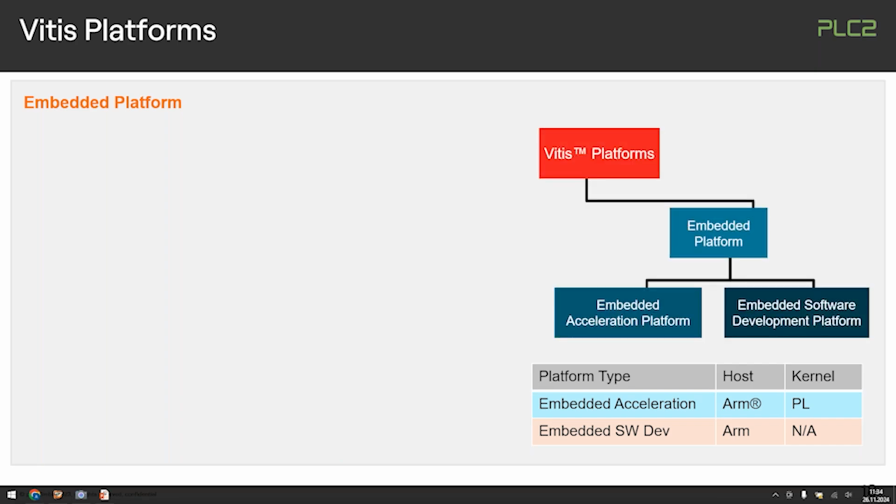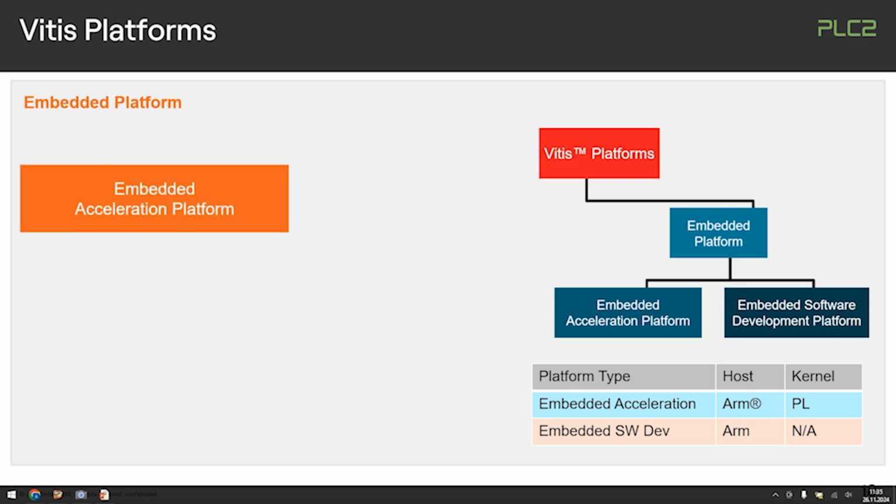And it basically means that you're picking up the platforms from hardware and building them into something that Vitis can digest as an extensible platform. So you would basically know in the end what ports, for example, of some AXI interconnect are already used and what are still not used, and how basically it can be upscaled to use these AXI ports for some internal interconnects. So that's the idea of this interconnection approach that Vitis takes to extend such an embedded acceleration platform, and that's really what we have in place.